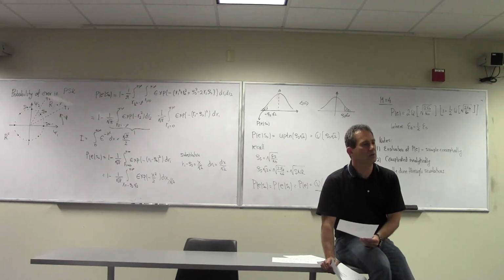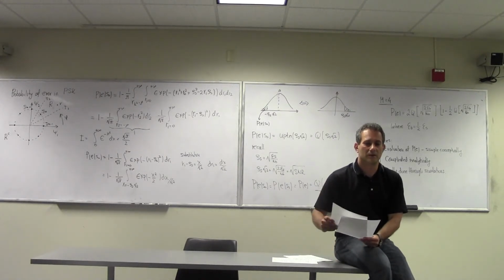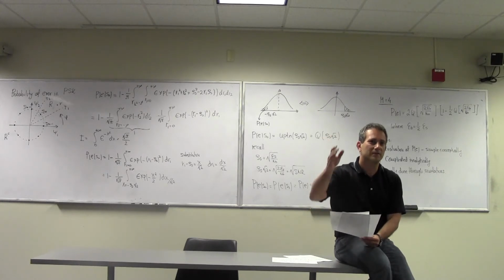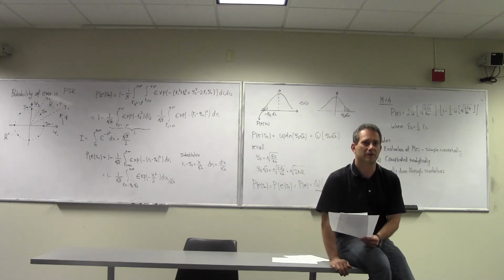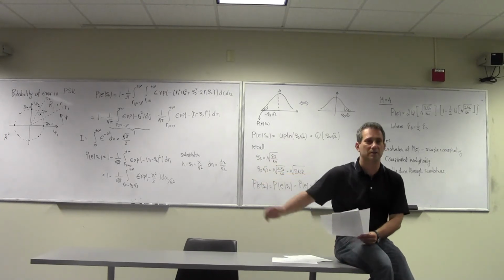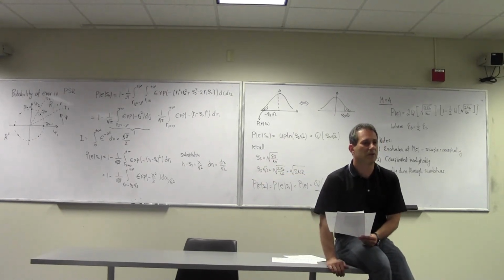So if you're trying to simulate, let's say, to determine the probability of errors that are on the order of 10 to the minus 6 or 10 to the minus 3, or whatever, you have to make sure that you throw enough darts so that you capture the probability, right? Let's say this equation predicts a probability of error of 10 to the minus 6, then if I throw 1,000,000 darts, probably one on average will be misplaced.